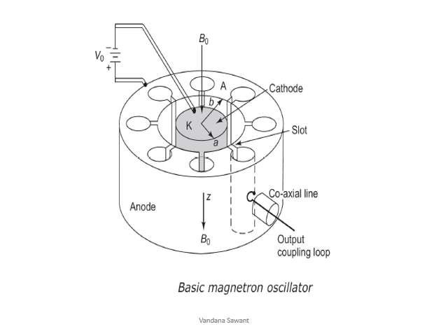So this Lorentz force is responsible for the movement of the electrons, giving the maximum energy to the RF field. Now see here how the processes take place. As we have seen, the magnetic field is in an axial direction, and the electric field in a transverse direction. There are many anode cavities which are connected to each other by the stripes. We can see the stripes connecting the cavities also.